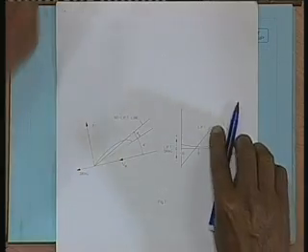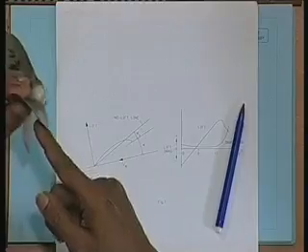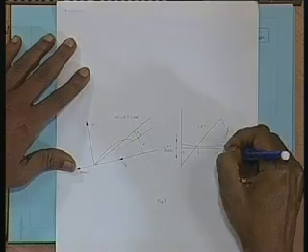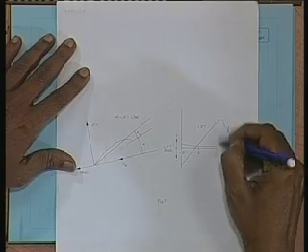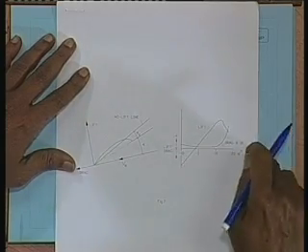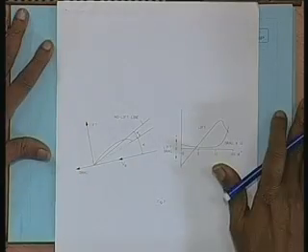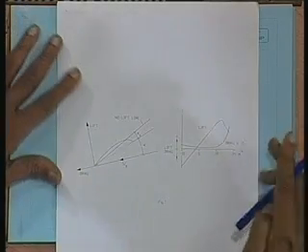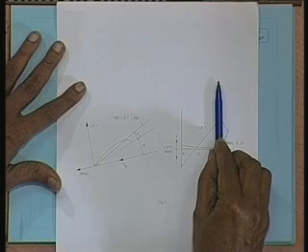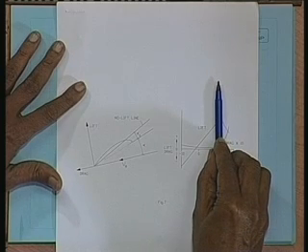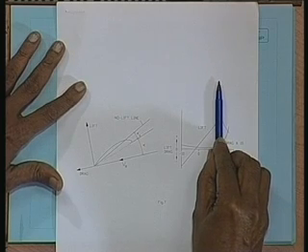That is, I get small lift if the angle is small, and if my angle of attack is more and more, I get more and more lift. But very strangely, beyond a certain angle of attack, this is angle of attack axis, lift suddenly falls. That means you do not get any more lift. Okay? This is called the stall angle.